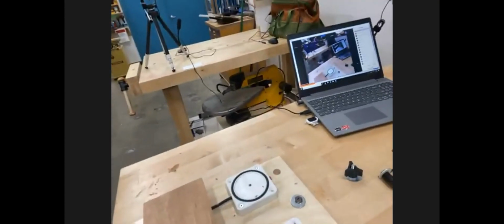Okay, so if you look at the foot switch, you see down there, there's a little filter right here. And that will filter out any sawdust or material that would be sucked in through the vacuum line. And that protects the system. If you look at the back of our vacuum pump system, and that's the way mine's built also, there's also a filter on the back end of the lines here. This one, by the way, needs to be emptied. But that's a problem that can happen with both vacuum clamping and vacuum pressing. If you just leave an open line there with the vacuum sucking, it's going to suck everything off your bench.